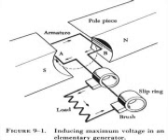Generator terminals, figure 9-21. Generator with interpoles. On most large 24-volt generators, electrical connections are made to terminals marked B, A, and E, figure 9-22. The positive armature lead in the generator connects to the B terminal. The negative armature lead connects to the E terminal. The positive end of the shunt field winding connects to terminal A, and the opposite end connects to the negative terminal brush.